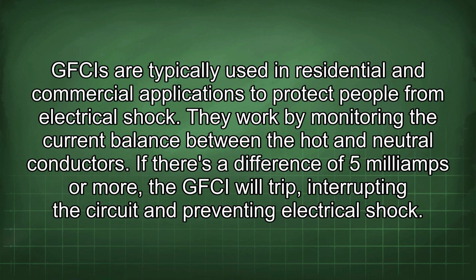GFCIs are typically used in residential and commercial applications to protect people from electrical shock. They work by monitoring the current balance between the hot and neutral conductors. If there's a difference of 5 milliamps or more, the GFCI will trip, interrupting the circuit and preventing electrical shock.